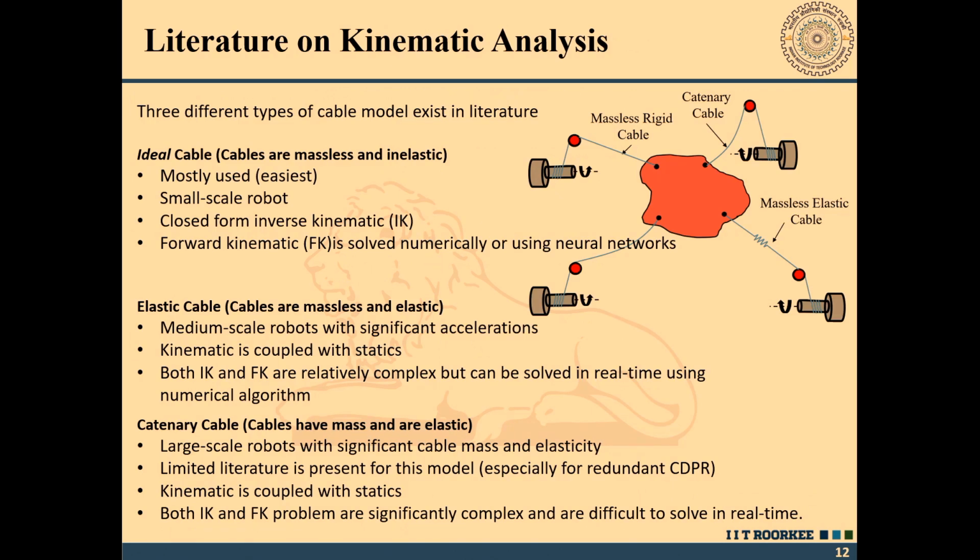When we looked at literature on kinematic analysis, there are different types of cable models. One is the ideal cable, where we assume that cables are massless and inelastic. Or there are elastic cable models, where the cable is massless, but has a certain elasticity.